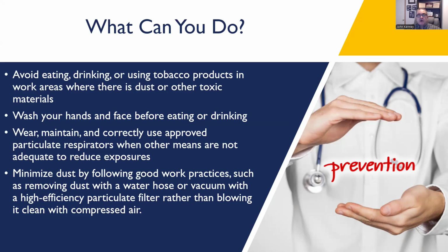Minimize dust by following good work practices, such as removing dust with a water hose or vacuum with high efficiency particulate filters rather than blowing it with clean compressed air. Again, a good wet-dry vac set up correctly that's meant for this, and you can buy them easily out there when you do run into this, will suffice and work.